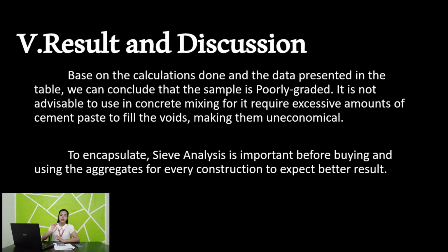So, if it suddenly goes from large to small, the gap is also bad. So our aggregates need to be well graded, with a complete set of sieves. To encapsulate, sieve analysis is important before buying and using the aggregates for every construction to expect better results. Supposedly, the standard before making a project is that you need to undergo sieve analysis to know that the aggregates or the sample is well graded.